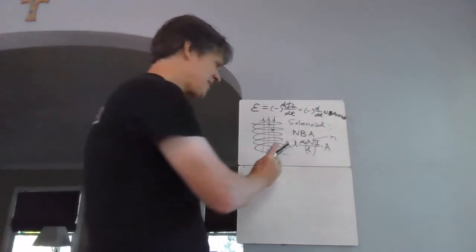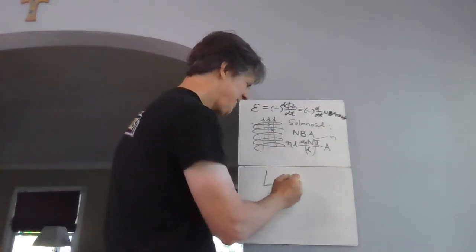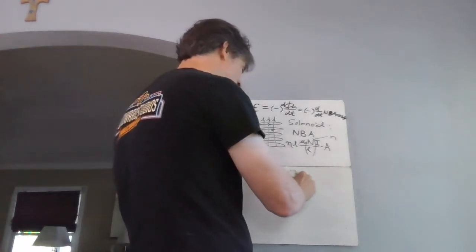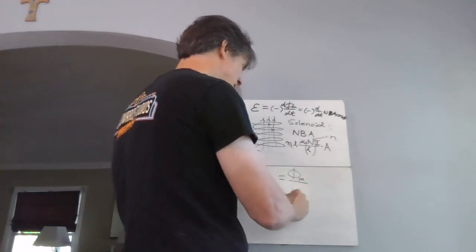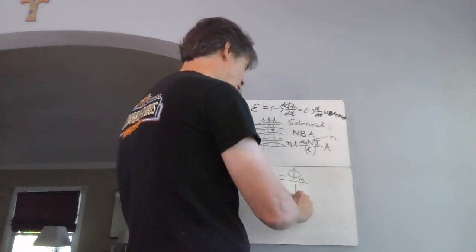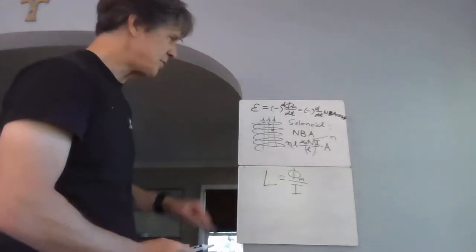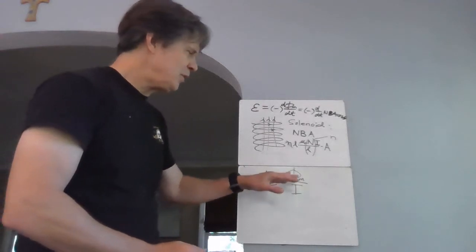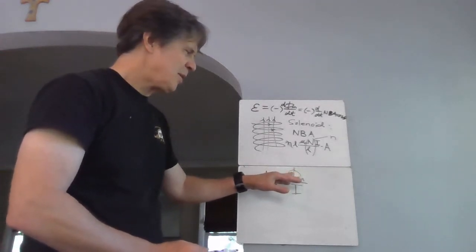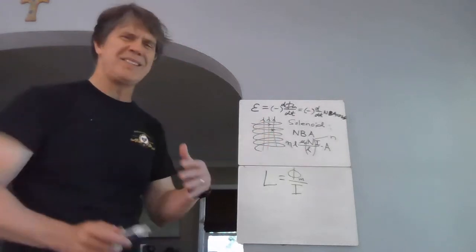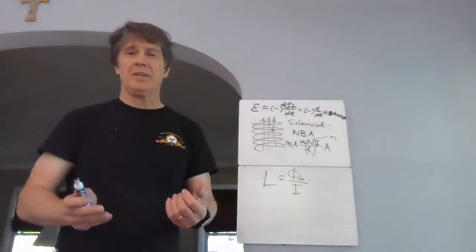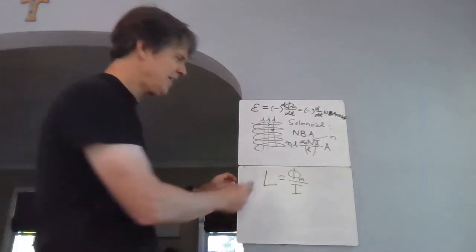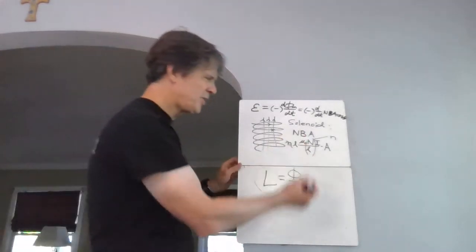And then I'm going to define this thing called inductance. It's equal to the magnetic flux divided by the current that's producing it. I haven't said this so brilliantly just yet. Here's the idea. You're going to get a flux because of the current flowing through there, but the more current you have, the more magnetic field you're going to have, and therefore the more flux. So this is a way of isolating the geometrical properties of the thing. You'll see what I'm doing right here.